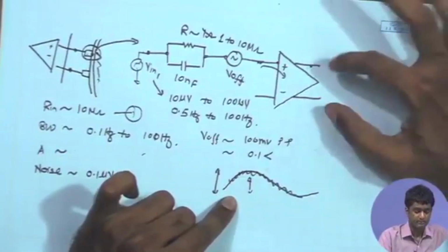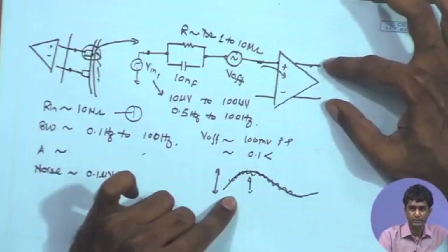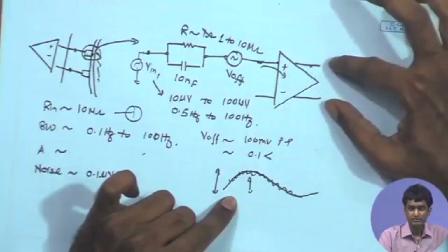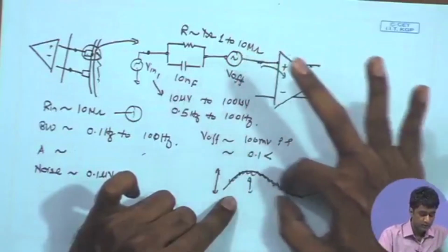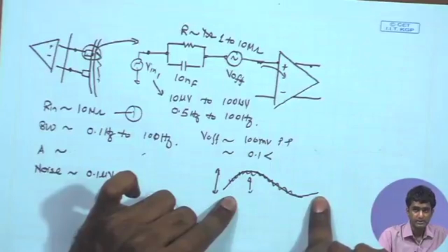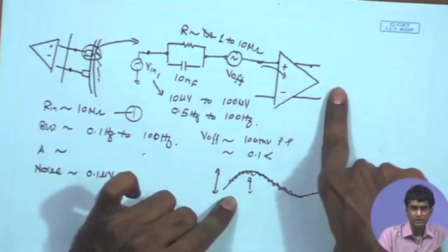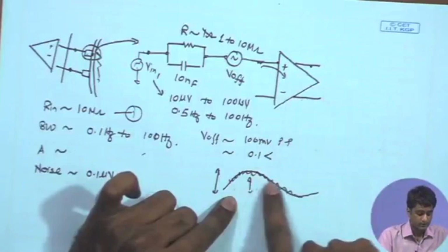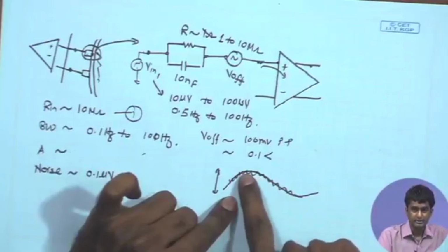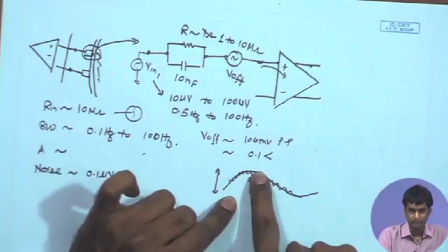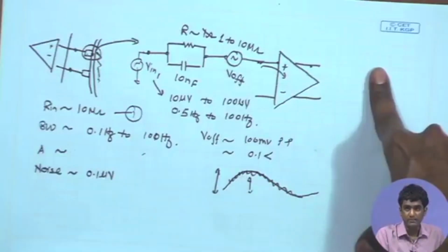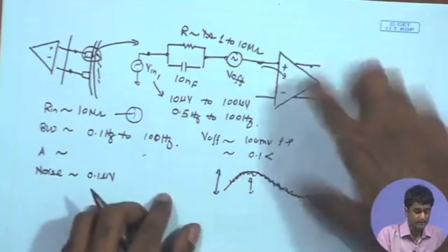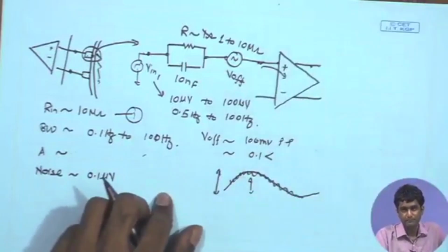So, if you are designing the amplifier with peak to peak output swing, maximizing the swing, in that case you can approach 1 volt. So, in that case if I have to accommodate this entire 100 millivolt peak to peak signal, I cannot afford to have more than 10 gain, because after that this signal will start getting clipped. If this starts getting clipped, then of course this tiny signal sitting on the top of it will also be destroyed. So, we do not want this large peak to peak signal to be clipped, provided it is able to pass through the front end amplifier.